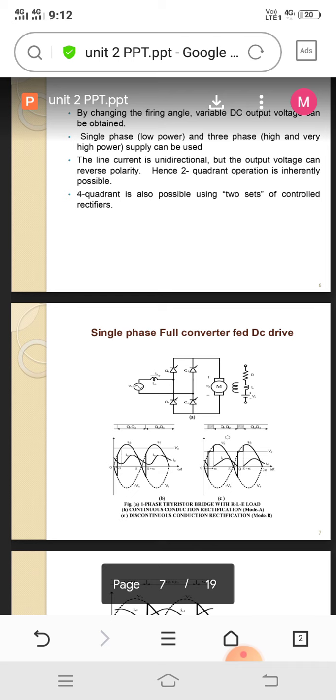Initially, we have to give the AC supply to the switches. The switches receive that AC supply, and during that time the switches have to be given gate pulses for on and off purposes. When the trigger pulses supply the proper gate pulses across the gate, the SCR converts the AC to DC.